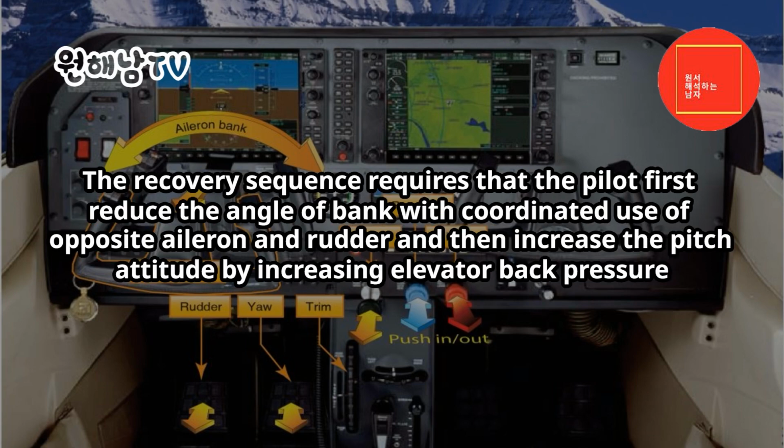The recovery sequence requires that the pilot first reduce the angle of bank, with coordinated use of opposite aileron and rudder, and then increase the pitch attitude by increasing elevator back pressure.